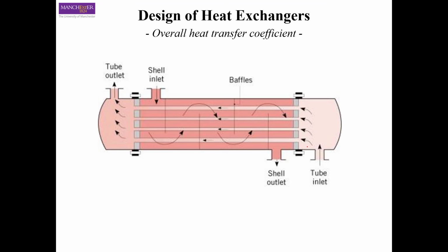So in terms of heat exchanger design, we are going to focus mainly on the shell and tube heat exchanger. But the concepts can also be used on other types of heat exchangers like the plate and frame heat exchanger or compact heat exchanger. So here we are looking at the shell and tube heat exchanger. I hope you remember from the previous lecture when we talked about different classifications. In a shell and tube heat exchanger, you have a bundle of tubes.